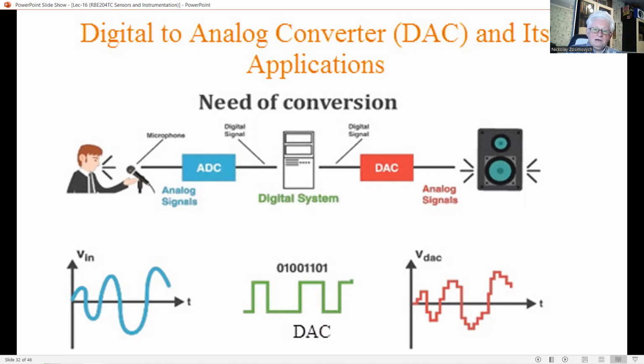The typical operation of the DAC chip is based on turning on and off of the semiconductor switch at proper times, as governed by some logic dependent on the digital data value. This switching will determine the output of an op-amp circuit, which is the analog output of the DAC. There are many types and forms of DAC circuits. The form will depend mainly on the DAC method, manufacturer, and requirements of the user or their particular application.